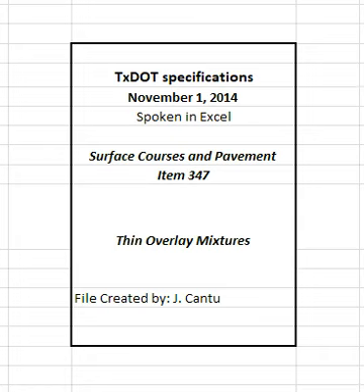4.7 Placement operations. Collect haul tickets from each load of mixture delivered to the project and provide the department's copy to the engineer approximately every hour, or as directed. Use a handheld thermal camera or infrared thermometer, when a thermal imaging system is not used, to measure and record the internal temperature of the mixture as discharged from the truck or material transfer device, MTD, before or as the mix enters the paver, and an approximate station number or GPS coordinates on each ticket.